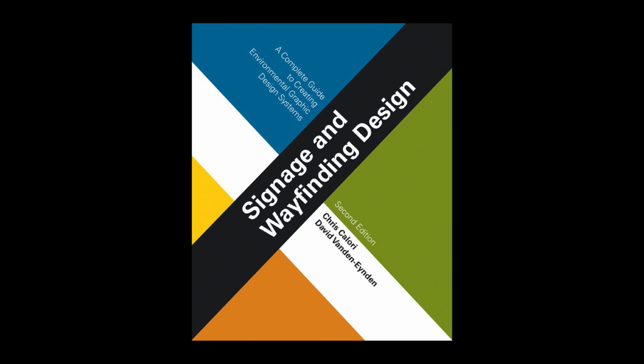During Phase 2, key signs may be numbered, but it is during Phase 3 that the sign numbering system for tracking all the signs in the overall project is typically established, as that's when all the signs in a program need to be located on plans and entered into a message schedule.